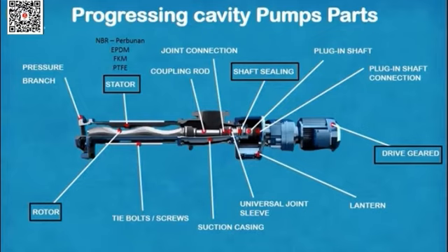The second component is the rotor. Depending on the work environment, they are made of annealed alloy carbon steel plated on the outside with a 0.3 to 0.4 mm layer of hard chrome.